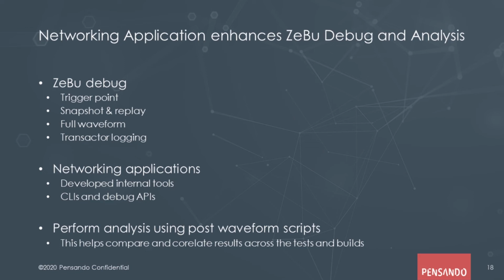Obviously, the full waveform option is always there. It is the slowest possible, but it definitely works. So if none of your internally developed debug tools or any of the other ZeBu debug works, then full waveform definitely comes to the rescue.